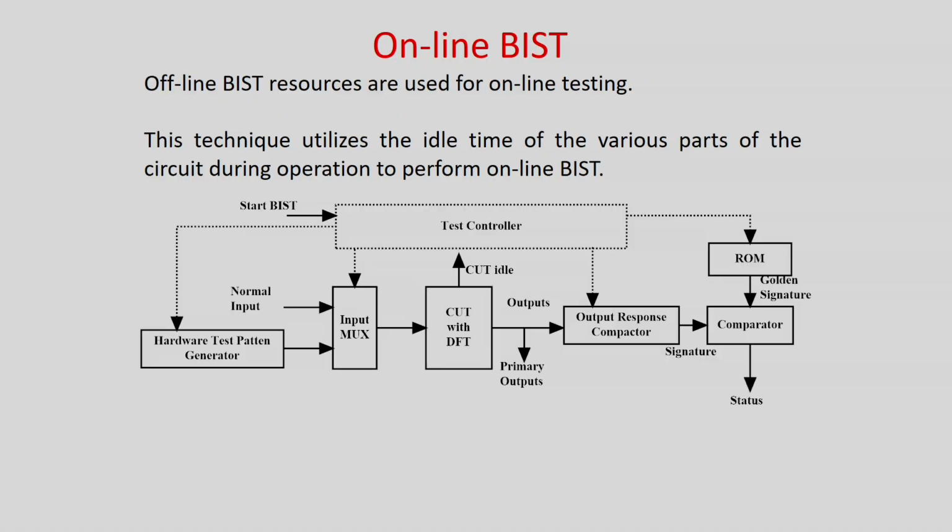Sometimes some circuit may be operating and some may be in sleep mode. So there is an important line they have brought out as the output called circuit is idle. If the circuit is idle for some amount of time, because the other parts of the circuit are working, in that case you can stop the normal input and apply the BIST. So this is actually called online BIST. Online BIST and offline BIST are very similar. In offline BIST, the circuit has not started its operation, so you just give the inputs from the test pattern generator and check whether the circuit is normal or not.